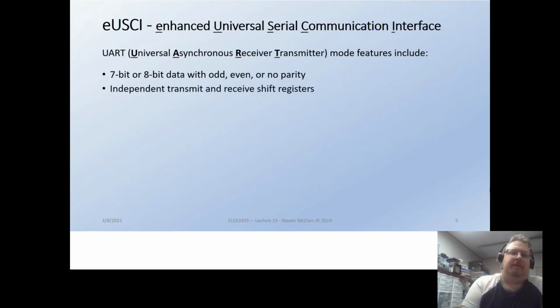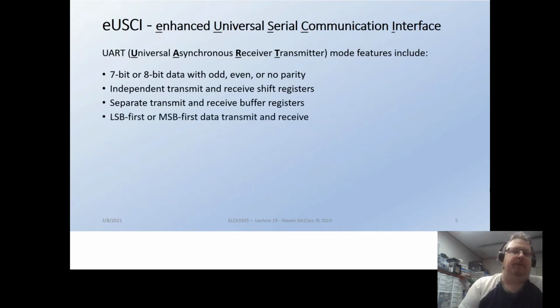It's got independent transmit and receive shift registers, so you can do a full duplex connection and be simultaneously sending and receiving data, and they just work. Separate transmit and receive buffers. You can do least significant bit first or most significant bit first, depending on which way you want to do it. So you can either have shifting from B0, B1, B2, or you can have B7, B6, B5, your choice.